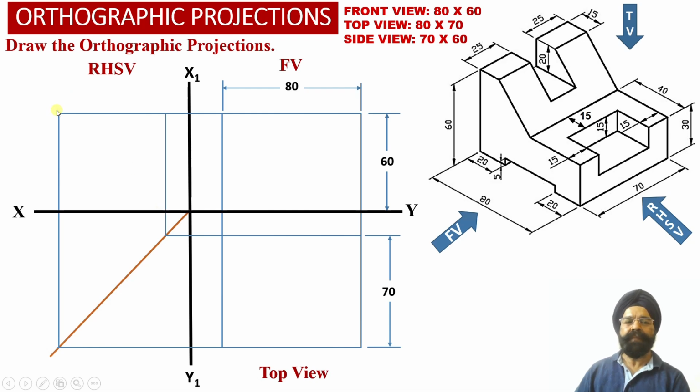So this way we have been able to obtain the right hand side view face of the solid measuring 70 millimeter depth of the solid, which we have transferred from the top view projections, and 60 millimeter height of the solid, which we have obtained from the front view projections over here. So now let us proceed to evaluate the front view orthographic projections corresponding to this engineering construction.